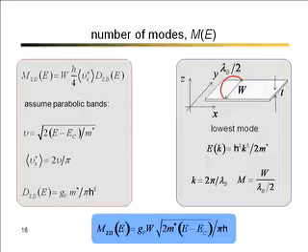Another way to think about this is that the electron has to be confined to the width of the channel. So the electron has a wavelength, and the electron wave function has to go to 0 at each edge of the channel. So what I'm showing here is that if I have a de Broglie half wavelength that fits into that channel, then that is one conducting channel, one lane on this highway that Professor Dada talks about.